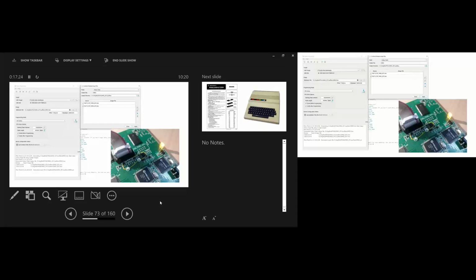So we programmed the E-squared prom. A little issue daisy chaining the two because we had to use 2 devices. But anticipating that, I put the link, so we just programmed one, got one programmed, and I got 2 pins wrong. My fault. If I'd read the 700-page document properly, I wouldn't have made the mistake.